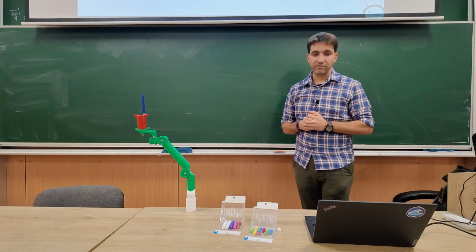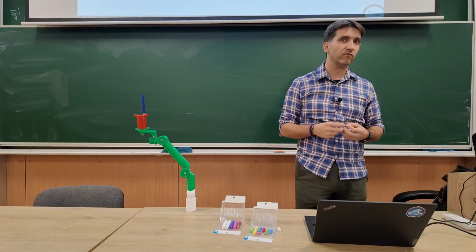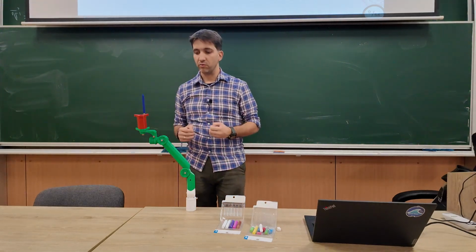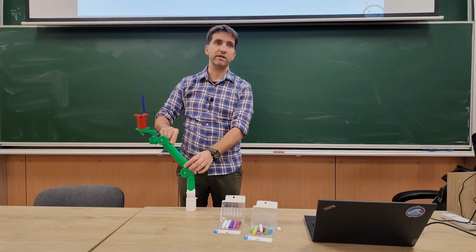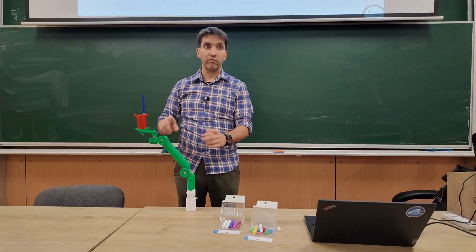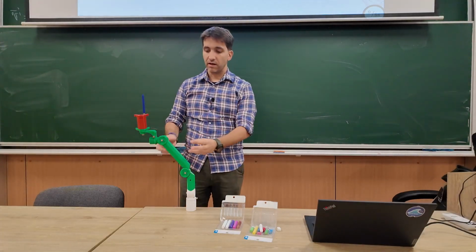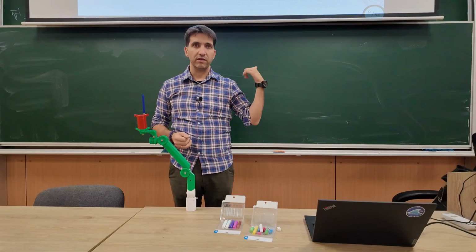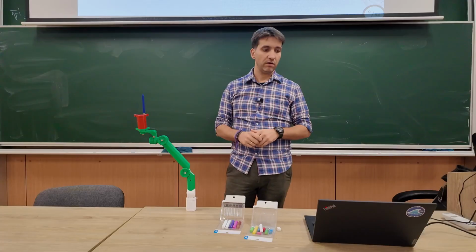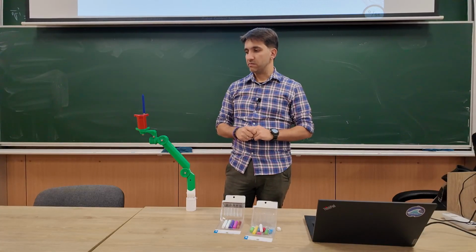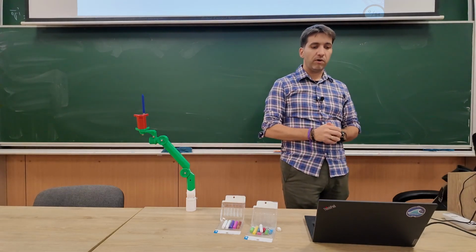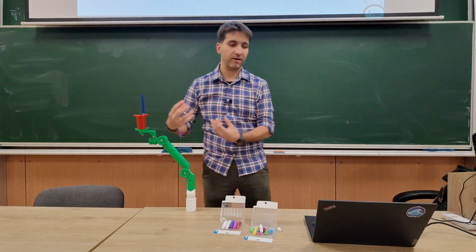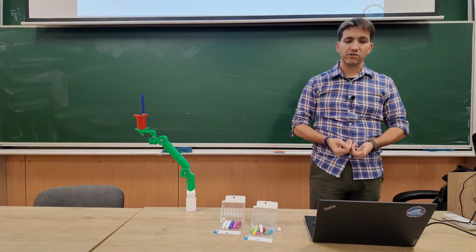All right. However, this kind of formulation is a little bit stiff for this kind of application. If we try to use Newton's equation to model the robot, we need to take each part of the robot, its link, as a separate body, calculate all the forces that act on the body, that's why we have the sum of forces, and calculate its accelerations. But these bodies are constrained relative to each other, and that's a bit complicated to model using Newton's second law of physics. I'm not going too much into detail, but you can think that we have to calculate all the reaction forces that happen at the beginning and the end of each link, and that's not straightforward. It's possible, but it's just not convenient.